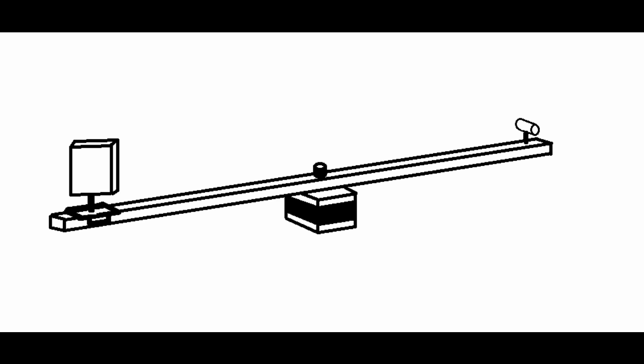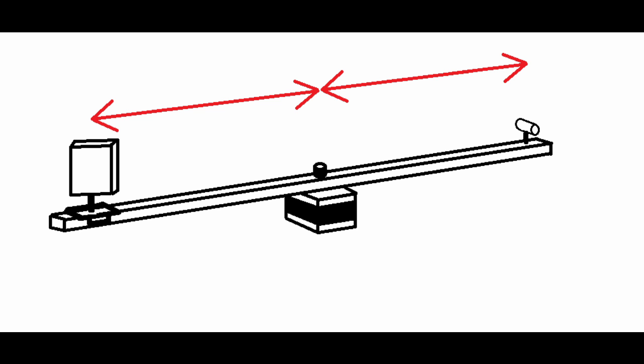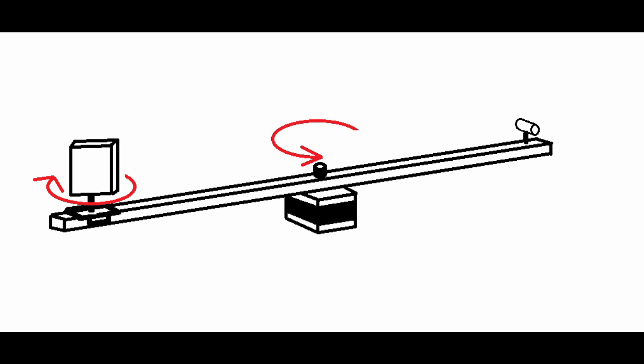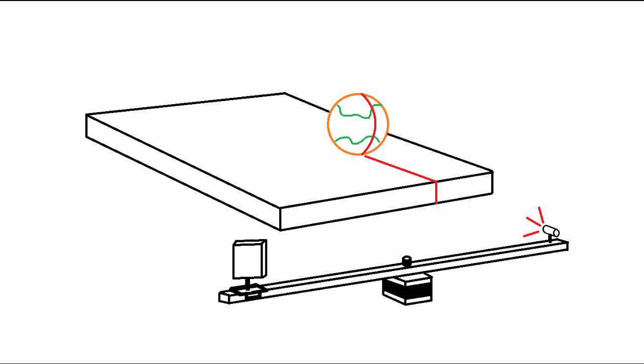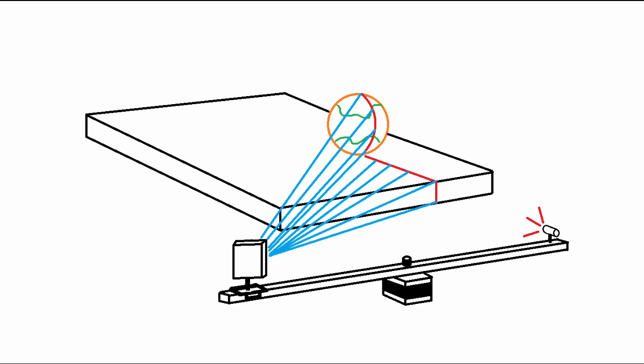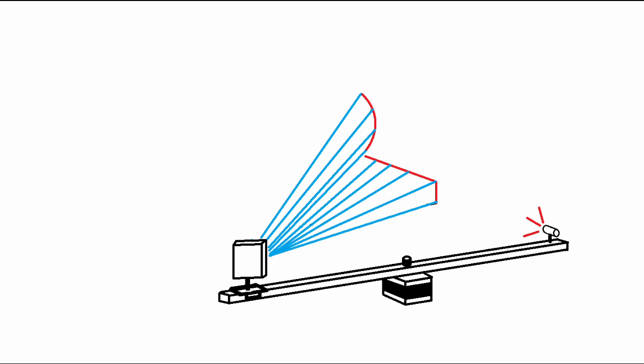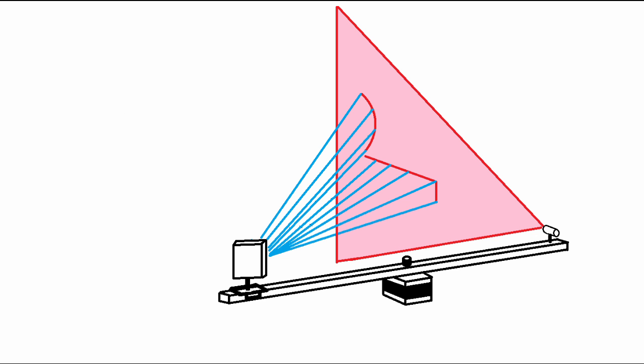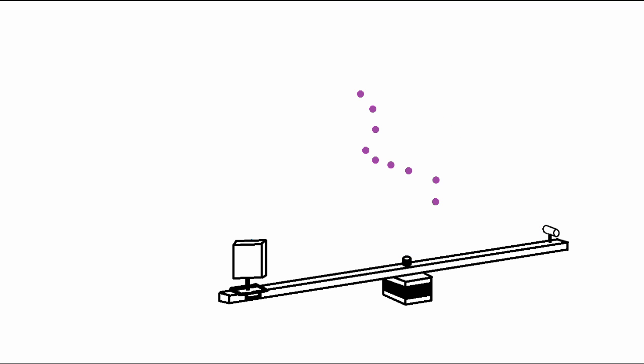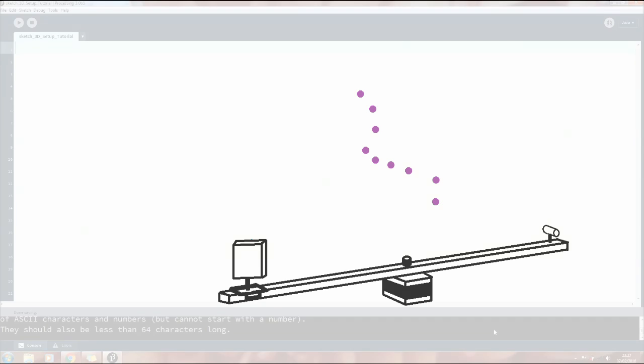So how does it work? Well, basically we set up a scene in 3D space using some key dimensions and angles relating to the scanner, the distance between the laser and the camera angle, etc. We then take those white pixel coordinates and use them to produce imaginary projection lines coming out of the camera. We then calculate where each of those lines intersect with the imaginary plane created by the line laser. At that intersection we can place a point in 3D space. We then do this for every white pixel and build up a 3D point cloud.